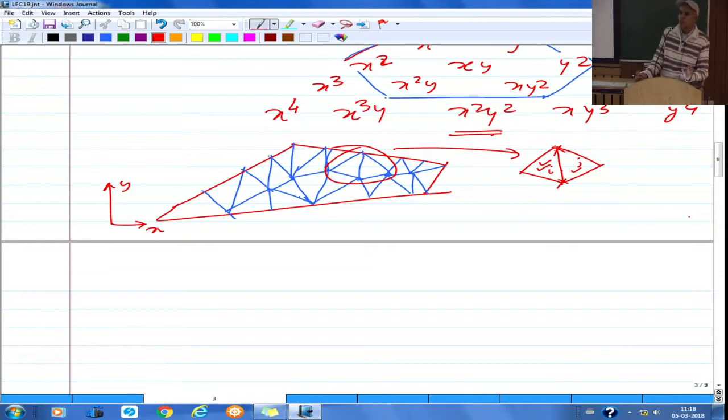In case of 1D, if the variable was the same at a node, at a point basically, then we say that the inter-element continuity or compatibility is satisfied. Here we require continuity of primary variables across the boundaries, in this case along this line. Within each of these elements we are assuming the temperature to be linear. So for the ith element, let us say the constants are in general going to be different for these two elements.